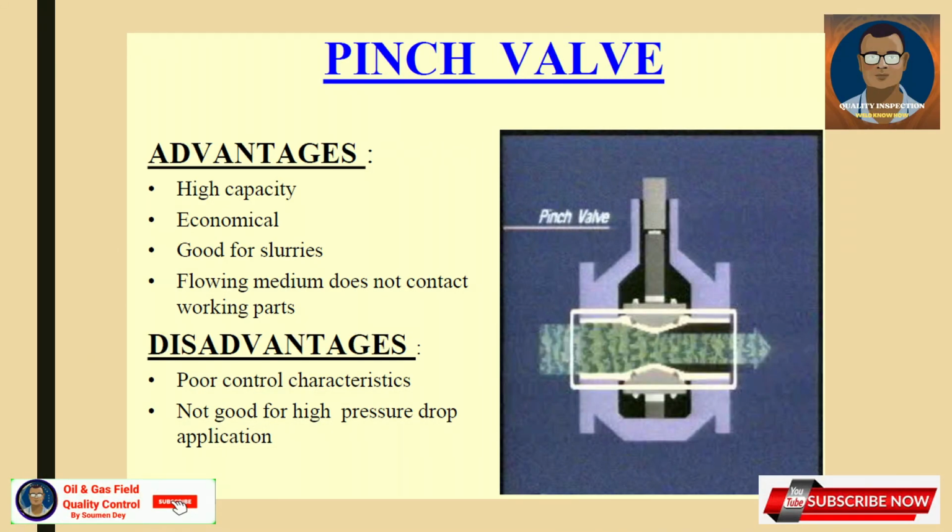Pinch valve. Advantages: high capacity, economical, good for slurries. Flowing medium does not contact working parts. Disadvantages: poor control characteristics, not good for high pressure drop application.